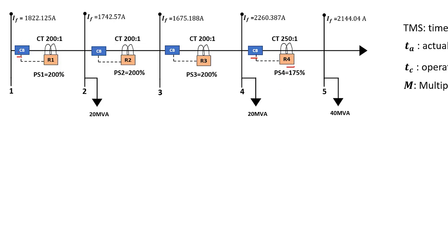So this one is the last one to trip when working your way up. The tripping time that you calculate here must not be greater than the tripping time for relay 1. So relay 1 should have the higher tripping time, so that protection is ensured from one section to another.